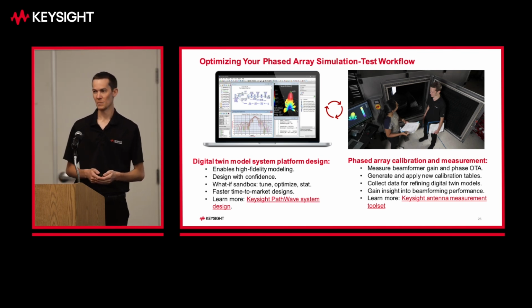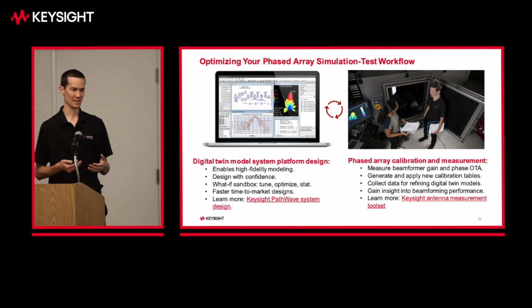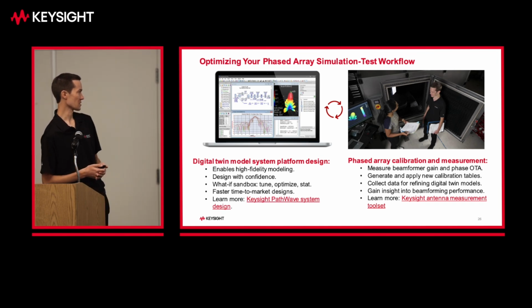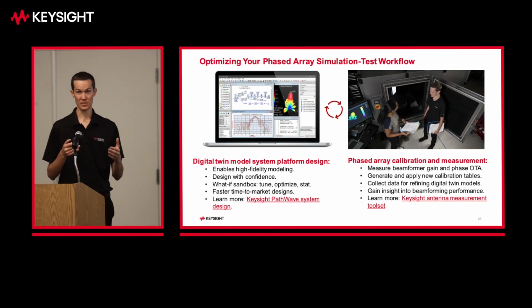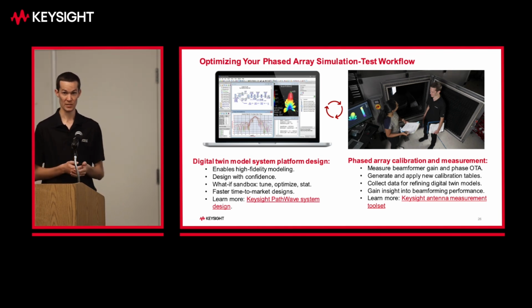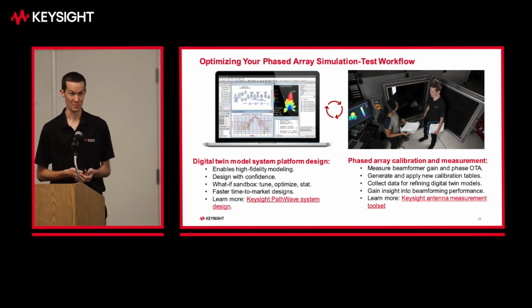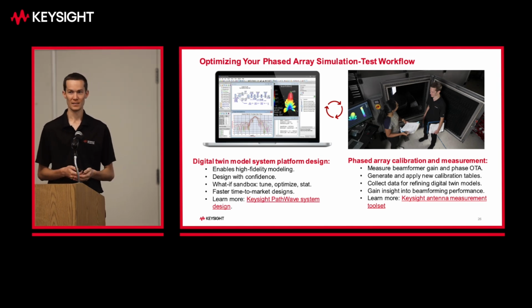So of course, this is about the entire phased array design workflow. We want to highlight the fact that measurement and simulation really do play complementary roles. As Mark alluded to earlier, the digital twin modeling enables you to design with confidence. It gives you a sandbox for testing and tuning trace lengths and maybe phase quantization in your phase shifters, to the point that you can get a pretty accurate estimate of what your array performance should be.